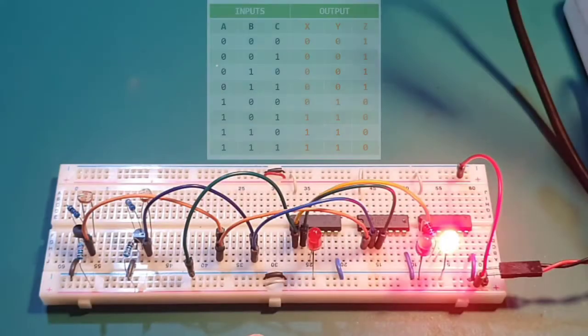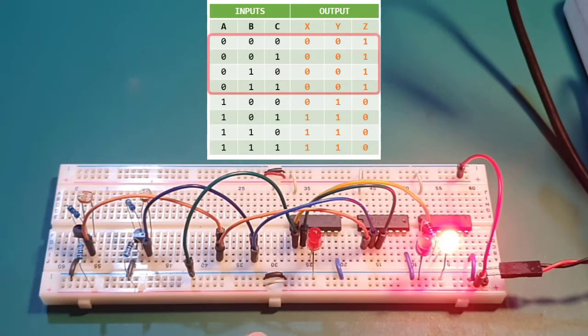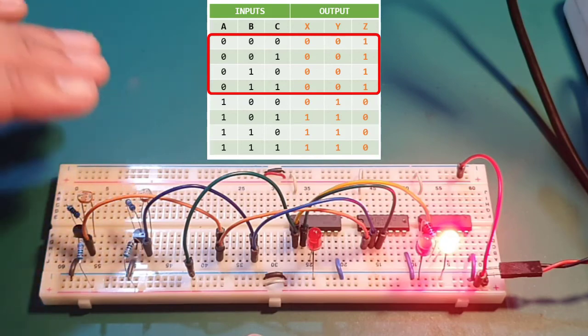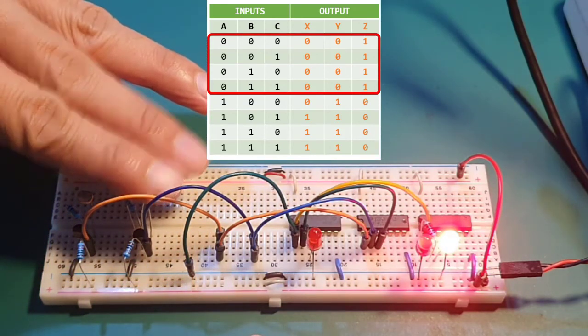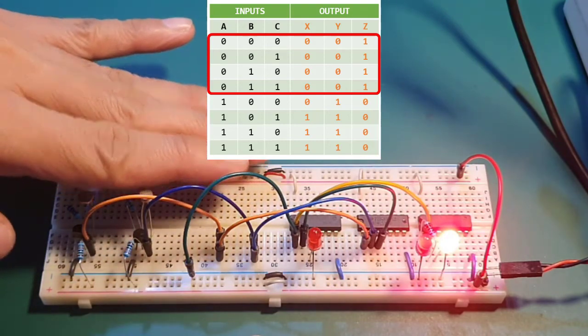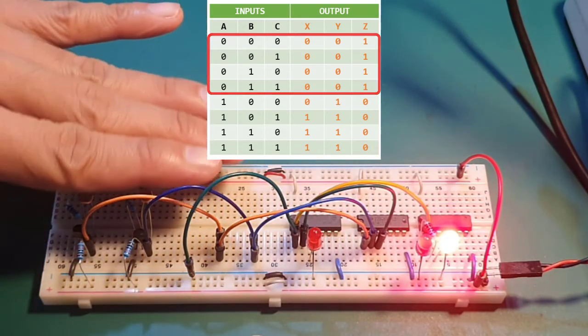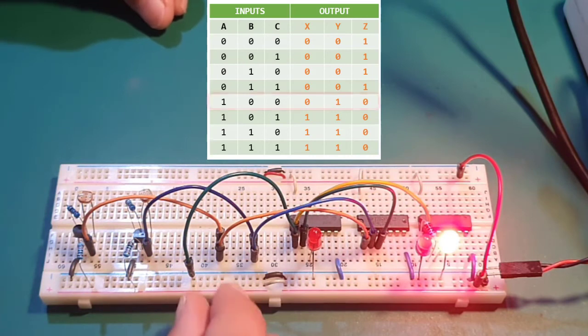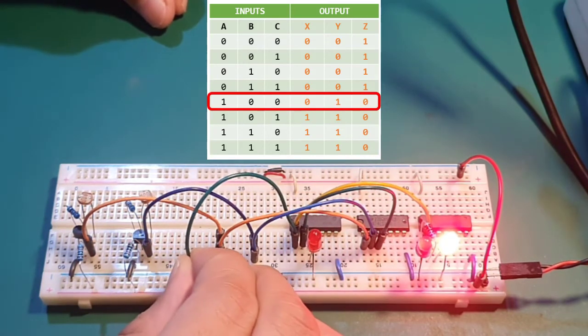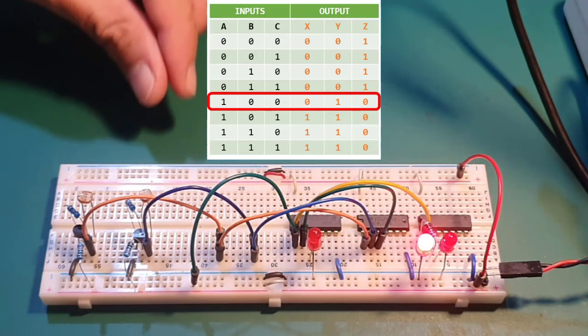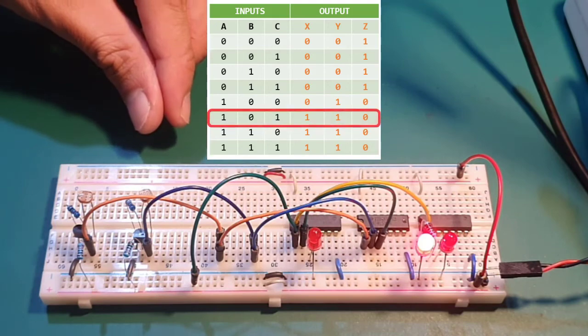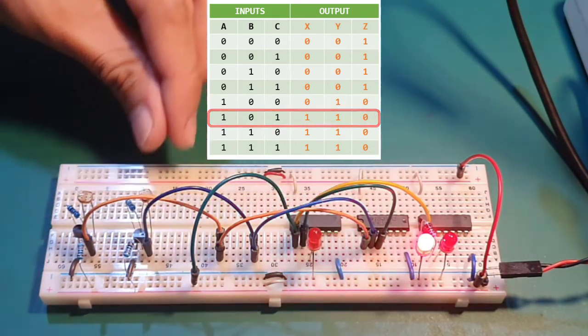As long as the main switch A is set to logic 0, the door is unlocked and the light bulb is turned off regardless of the value received from these two light sensors. But as soon as the main switch is set to logic 1, simulating that the device is activated, then the door is locked. But the light bulb only turns on if at least one of these sensors senses dark surroundings.